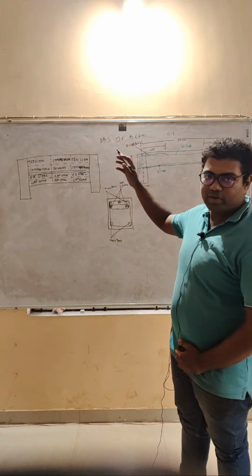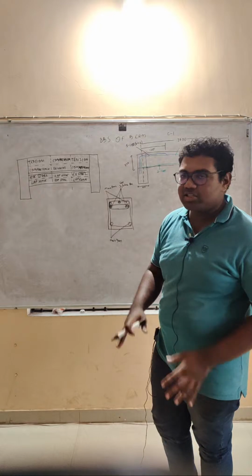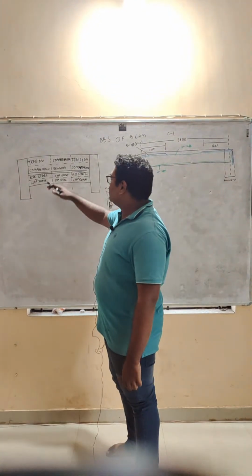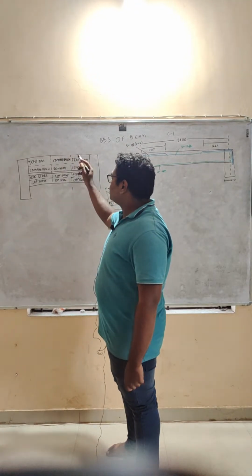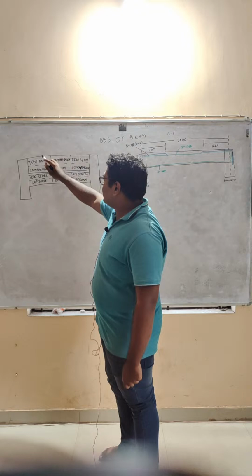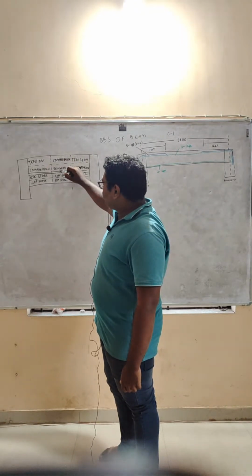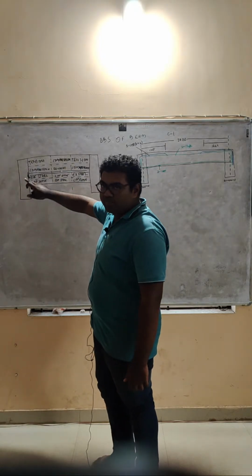Bar bending schedule of a beam. Before we proceed to our calculations, we need to get some basic things clear. Whenever a load acts on a beam, the upper center portion of our beam develops compression, while its adjacent sides develop tension. Similarly, the bottom center of our beam develops tension, but its adjacent sides develop compression.